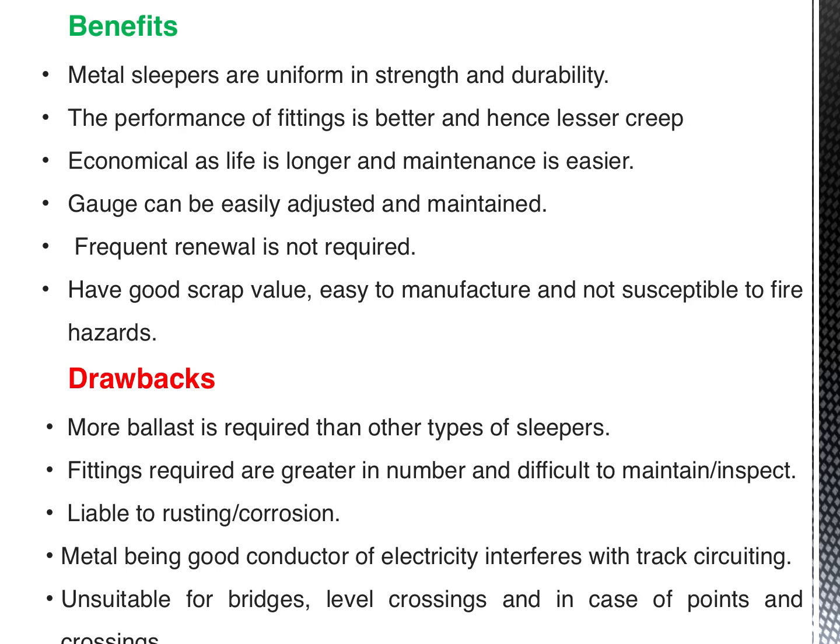And metal, being a very good conductor of electricity, will sometimes interfere with the track circuiting. These sleepers are very unsuitable for bridges, level crossings, and in the case of points and crossings. And these are suitable only for stone ballast. So if you are using any other ballast layer, the use of metal sleepers is not advisable.